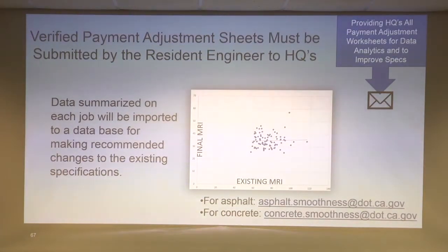So this was the Highway 50 project, one of the lanes that went from Sunrise Boulevard up to El Dorado Hills. Most of their pavement that they were milling and filling was in the 60s to 80s. Some of it was close to 100. They paved all that back, and they had one in that lane that was 58. That's smooth. Most of their paving was in the 30s and 40s.